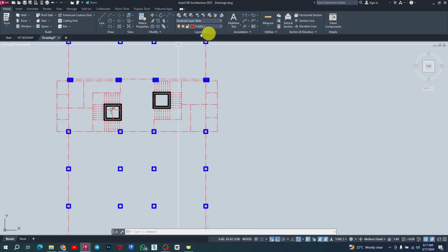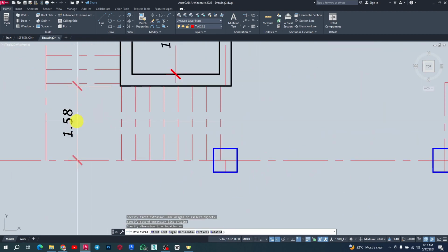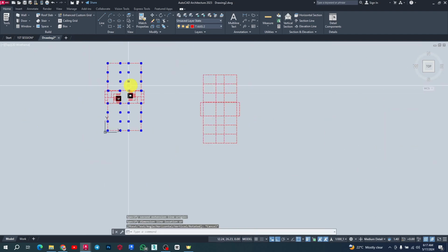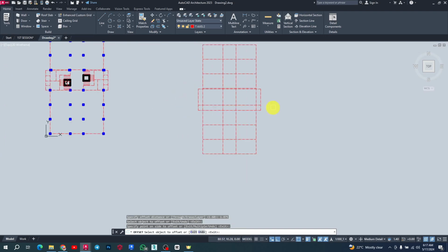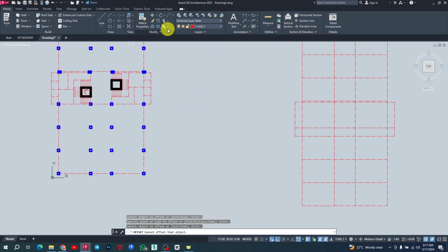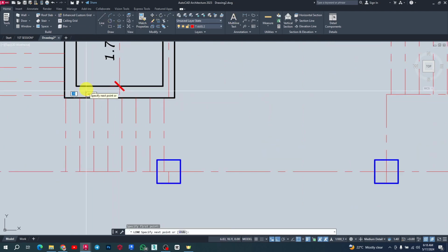Once we are here again, we want to include this staircase position here. So we have 1.875. You have to add that to have the first flight. So I'm going to go down here and include it. 1.875. I'm including half of the thickness of the wall to it. That is 15 divided by 2 is 0.075, right? So I'm going to take this one here, and then I include, let's say from the center line of this one. So let's try to measure out the center line to this.